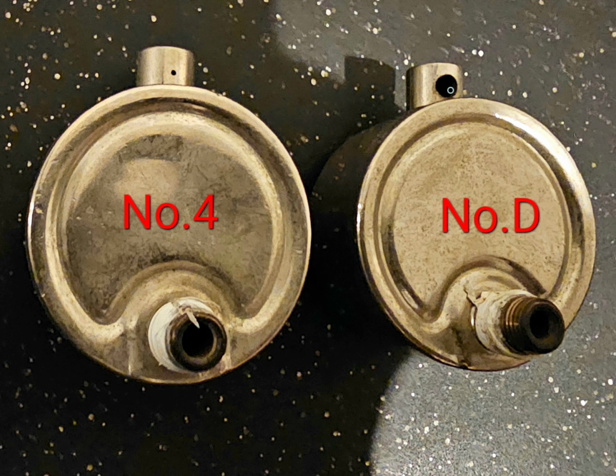But this vent here would be more so used for a riser pipe. It serves better for a riser pipe. However, it might not be a bad idea to use this for a cast iron radiator that has a harder time heating up. And the reason why I say that is because, if it's a cast iron radiator, even with it not having the drop away pressure, just the way the radiators are set up, they'll hold the heat for a long period of time and you're not going to notice any heat loss.